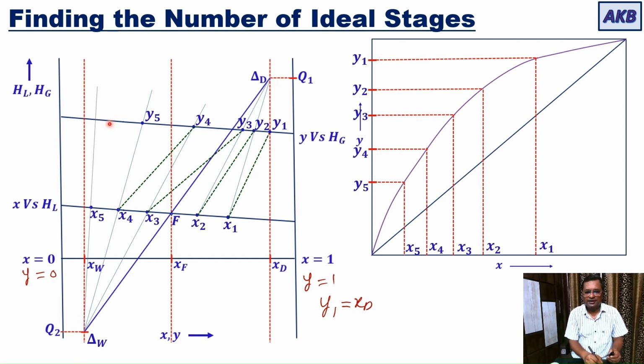and intersects the upper curve. So you are drawing the construction line. In that process, you get this point. You read the x coordinate of this point. That will be y6. Before that, you have to connect x5, y5 with a tie line. Then you get y6. Read y6, get the value of y6, go to the distribution diagram and get the corresponding